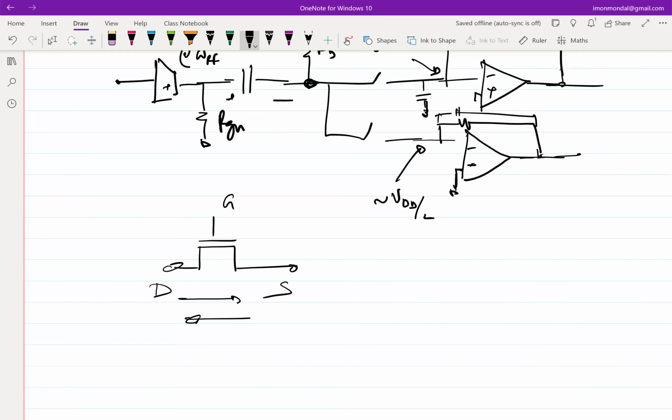Right? It's a sinusoidal input. So the effective current, if it is zero bias, the total current can go either on the left or the right. Assuming there is a DC current into the switch. But if there is no DC current, which typically is the case in a switch, then the total current can either go left or the right instantaneously. Does that make sense? Which means the drain and the source keep on switching. So then from where will you connect the body? You cannot, right? So what is the solution then?